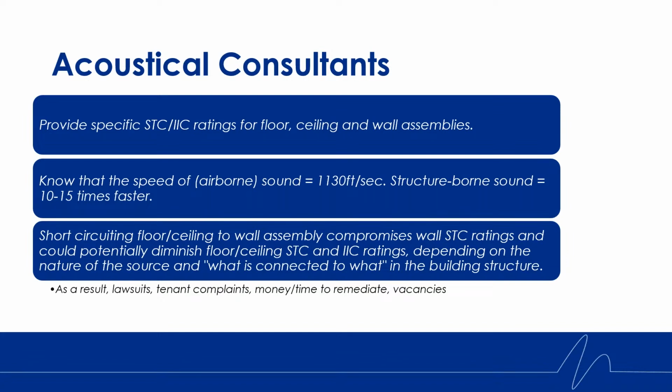So you can imagine, once that impact noise, whatever the source, gets into the guts of the building, that sound is traveling at a rate of about 15 or 16,000 feet per second. So we have our short circuiting of the floor ceiling systems to the wall assembly, compromising the STC rating of the wall and or the STC and IIC rating of the floor or ceiling, depending on the nature of the source, as I talked about on the previous slide.